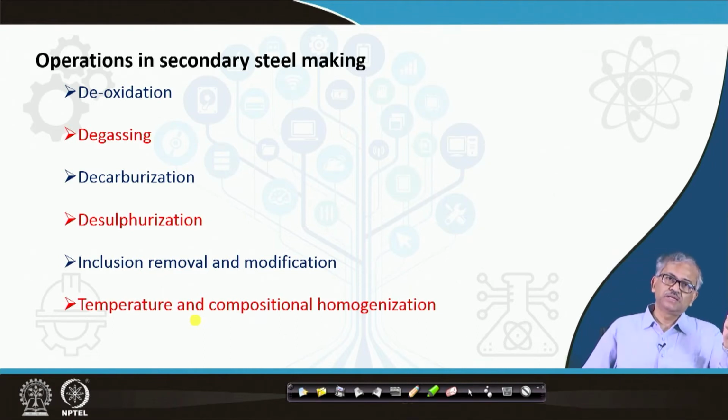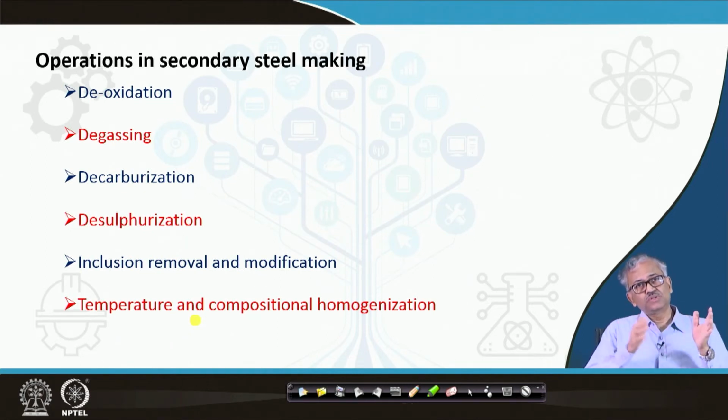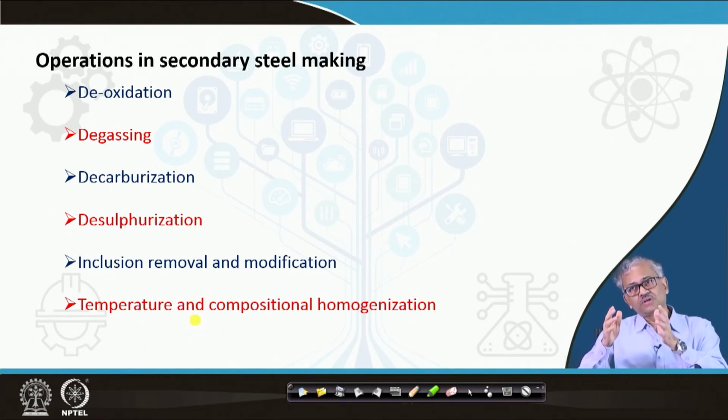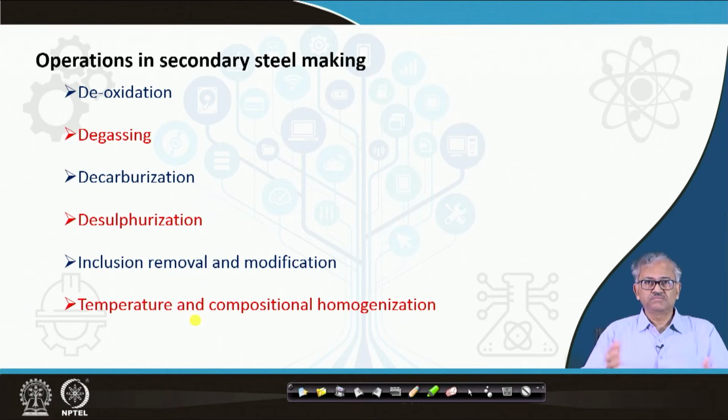And when it is tapped from the LD to the ladle, it is called the tapping operation. During the teeming operation, when the ladle goes from the SMS and is kept on hold for some time, a lot of thermal stratification takes place, because the ladle loses heat from the side wall and from the top. So the center will be at a higher temperature and near the wall it will be at a lower temperature. The liquid will then come out at different temperatures unless you homogenize the bath.